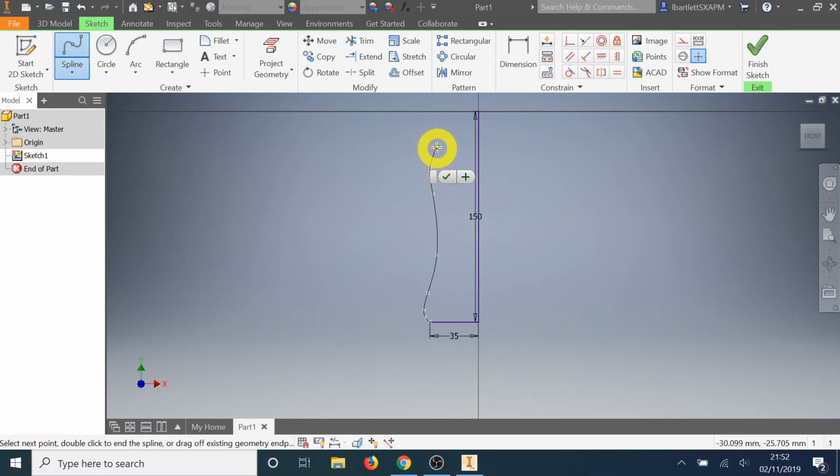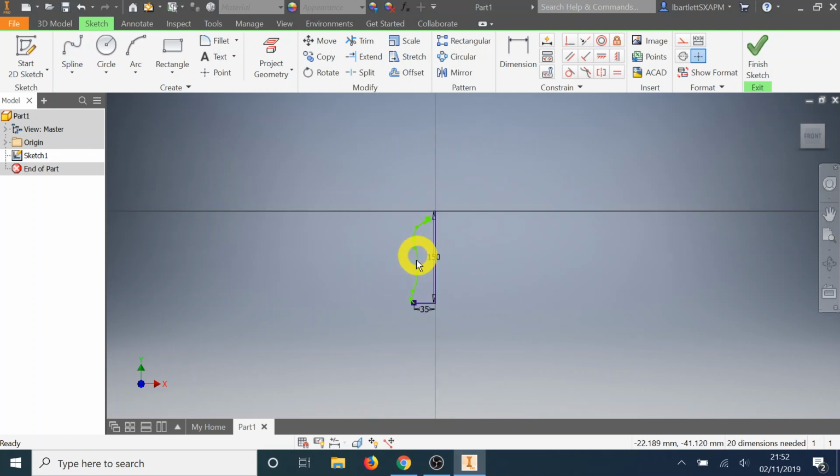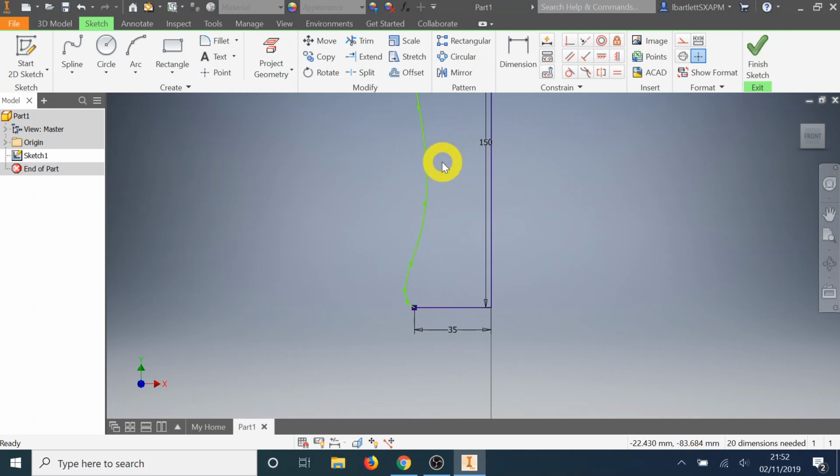Now I'm going to start bringing it in so I can get to the mouth. I'm going to want to zoom in a bit here because I want it to go up a little bit. It's going to go up to there. And maybe a tiny bit more up, right? That'll do there. Now I'm happy that that's kind of a curve I want for my shape, so I'm going to click the tick button here that appears. So tick, and we've got our shape. So my bottle's going to follow that shape there.